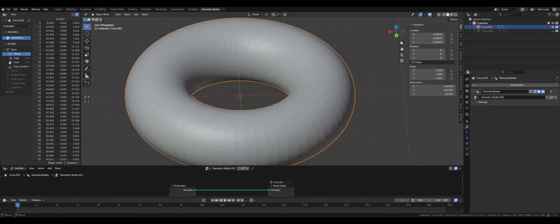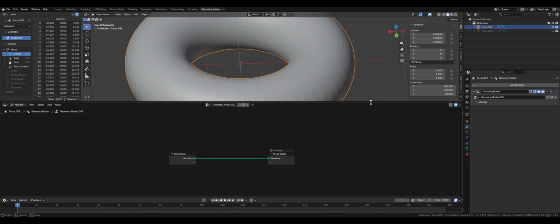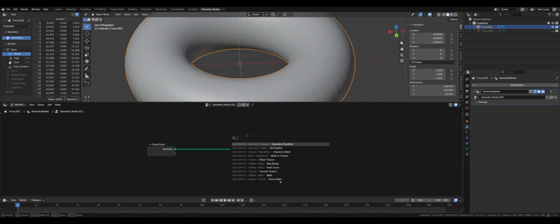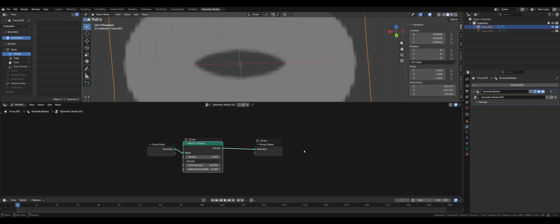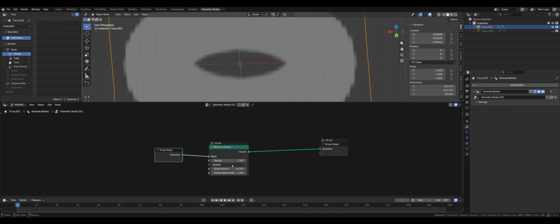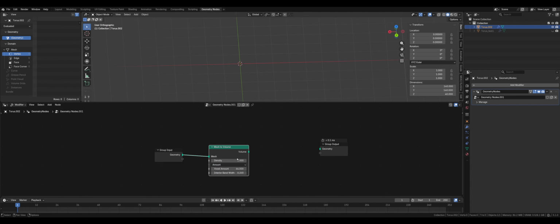Okay, so let's remesh this torus at a certain size. Here, I've set space to be the search function. You may need to change your preferences to do this. So what I'm going to do is mesh to volume. This turns it into a volume, and you can then change the size. I'm just going to quickly disconnect that, because you don't want to accidentally put the wrong size in and again crash your computer. So size 0.3 is okay, but for this let's change it to say 0.6.